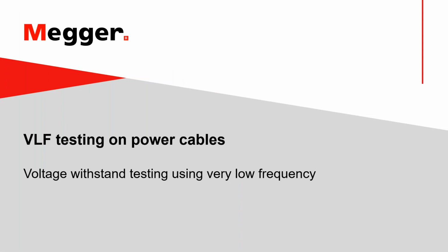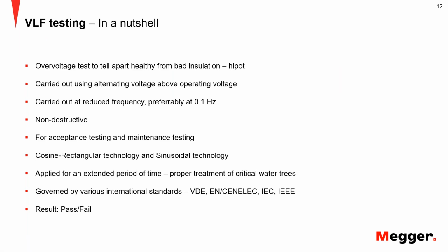And now to VLF testing. So first of all, what is VLF testing? Well, it's very straightforward. It is nothing but a high-pot test. It replaced the DC high-pot test. It's an overvoltage test that pretty much tells you I have good insulation or I have bad insulation, and the judgment is the cable holds or the cable fails during the test. It is done preferably at 0.1 hertz.